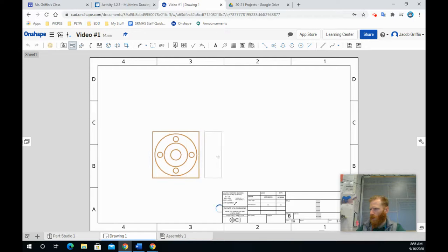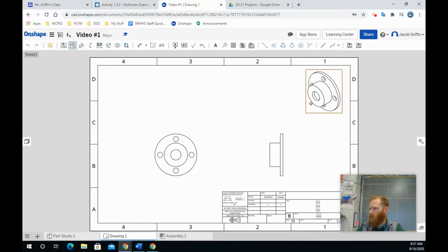And then when we pull it out, it will give us our right side view. And if we needed to beyond this, we could pull it up and get a top view. But with this piece, both of those views are going to be the same. So we're just going to keep our right side view. Right, and before we exit, we need to click on that front piece one more time because we need an isometric view. And these live up in the corner. Right. Oh, we want that isometric view, and then we can hit escape.